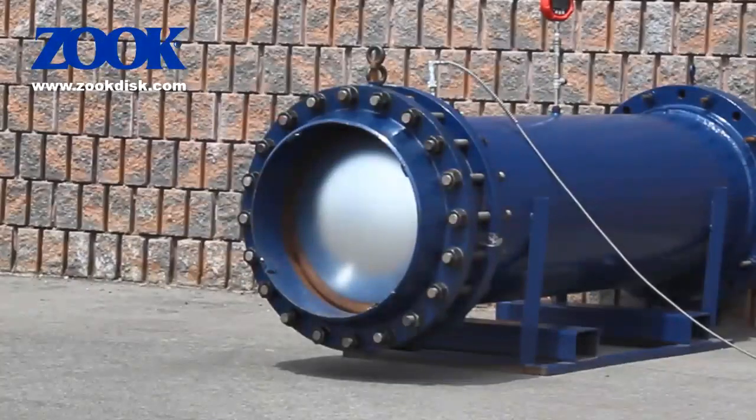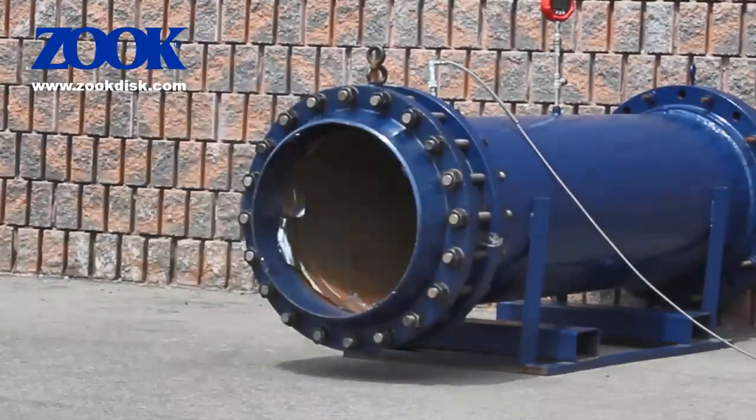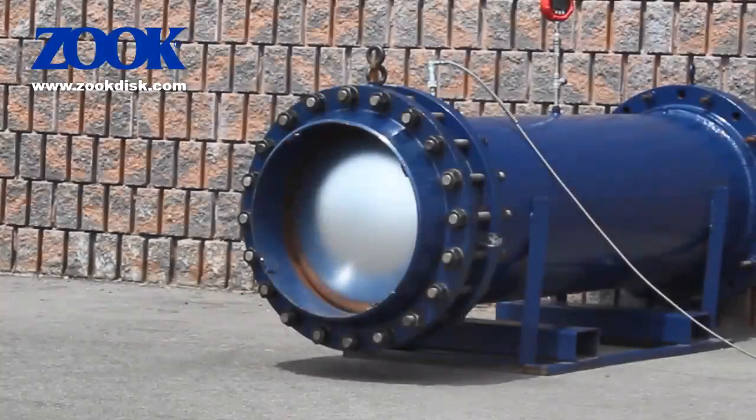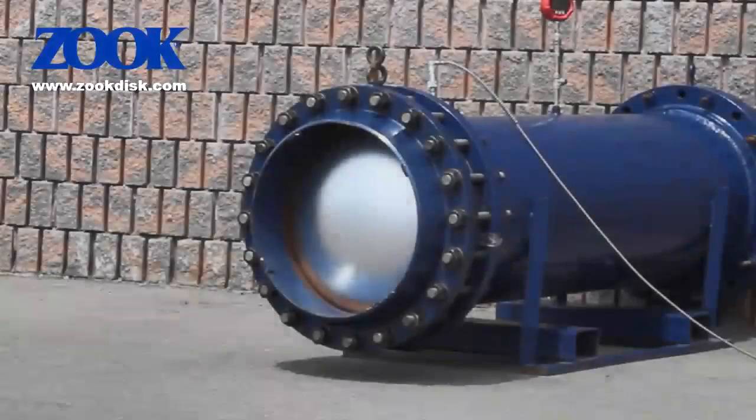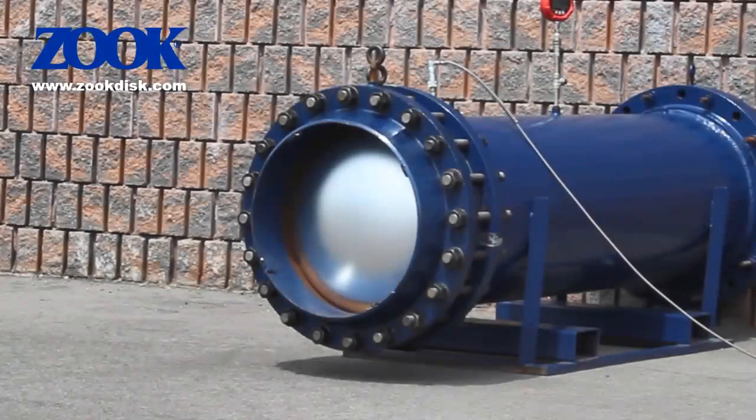Here, you can see a rupture disk mounted to the end of a chamber, which is sealed at one end, and a rupture disk mounted on the other. Pressure is introduced into the chamber, and the disk bursts or opens when the pressure differential reaches the set point of the disk. Differential pressure simply means the pressure on one side of the disk is higher or lower than the other.